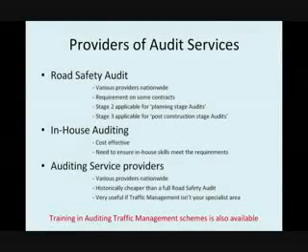So, given the processes that we've just looked at, where can we get this and what providers are there of temporary traffic management auditing? Well, first of all, there is a formal approach called road safety audit, which there was a seminar on a couple of hours ago in this venue. There are various providers nationwide of road safety audit. It's a requirement on some contracts to have a road safety audit, certainly a stage 2 road safety audit at design stage to audit the drawings and the plans and the risk assessments and method statements that have been produced and ensure they're to the standards outlined earlier.